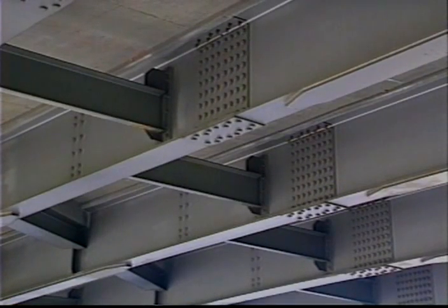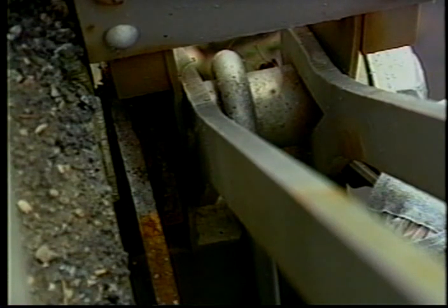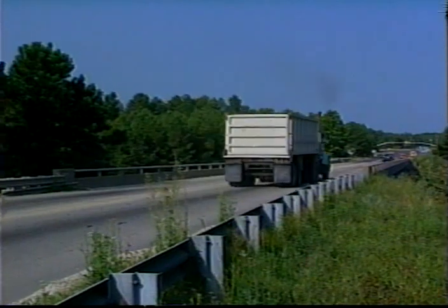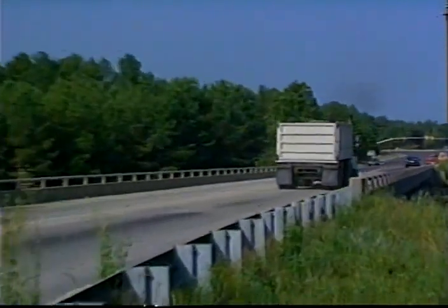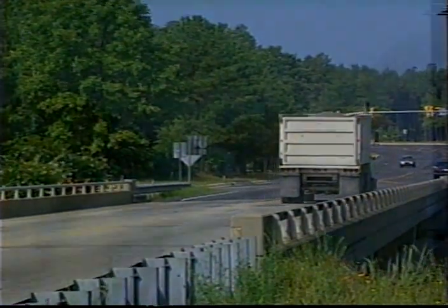Connections are critical to bridge construction and strength. Because they are points of discontinuity in the materials, members with deficient connections are often the cause of failures. Connection failures can be just as catastrophic as failures in structural members. Bridges are designed for certain types of vehicles to simulate actual loadings. Overweight trucks that use a bridge repeatedly can cause a phenomenon called fatigue.